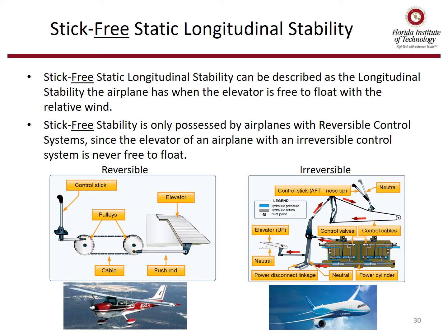And again, only aircraft with reversible control systems have stick-free stability. Because with an irreversible control system, the elevator will never float. It's never free to float.